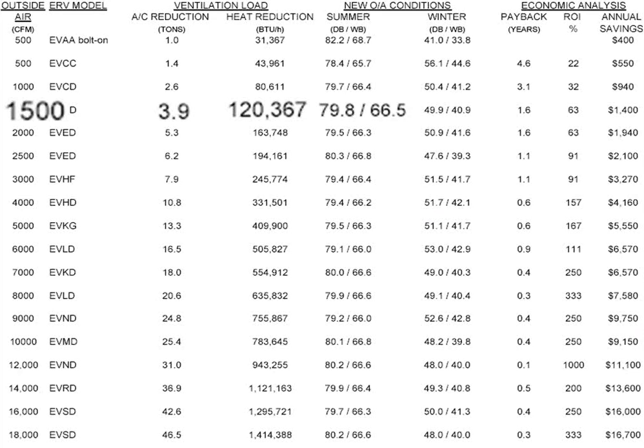80, 67 is the temperature at which air handlers and rooftops and fan coils are designed at for incoming air to the evaporator coil. So if I get it down to 80, 67, it's almost as if there is no outside air load at all. I basically have reduced the outside air to match what a typical return was supposed to be for that equipment anyway. So it's like having no outside air.